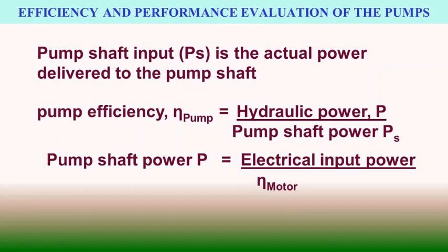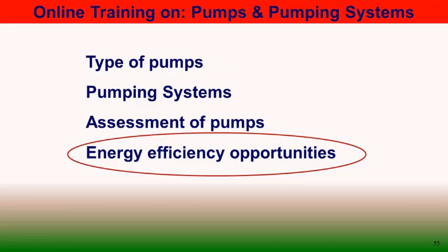There are certain practical difficulties in assessing the pump performance. We may not have the pump specification data like performance curves, and most companies do not keep the original equipment manufacturer documents that provide these data. So how the pump is loaded and how the pump flow is calibrated with reference to the head across the flow passage is only estimated, and accordingly it is modified or taken care of.